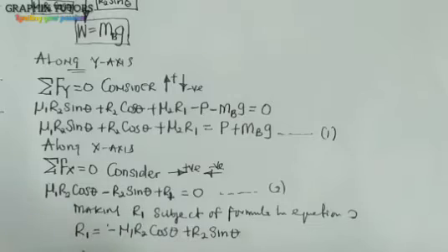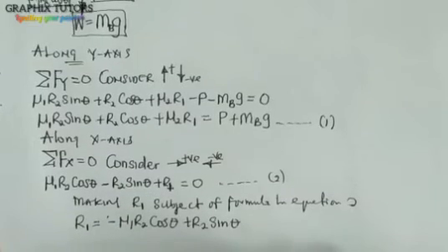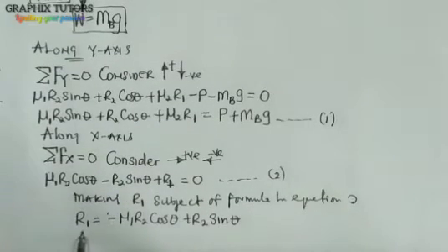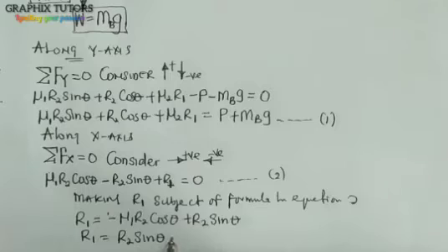Now we've gotten this. I can rearrange it, so we have R1 equals R2 sin theta minus mu1 R2 cos theta. Now the way it is, what is common here? I can bring whatever is common out, or I can just leave it this way, right?